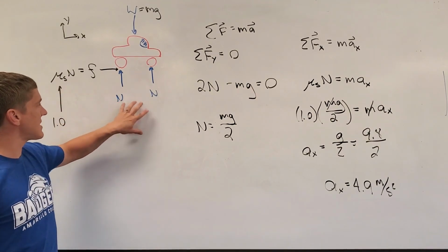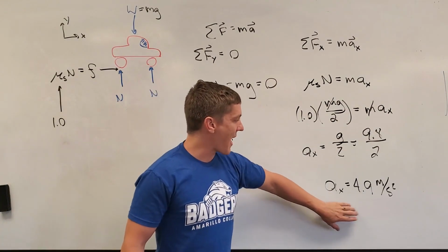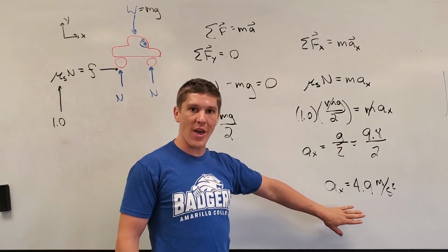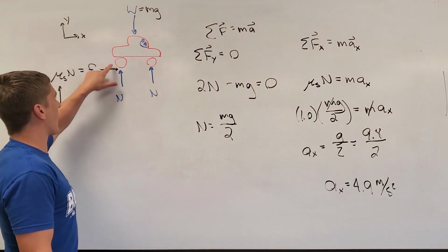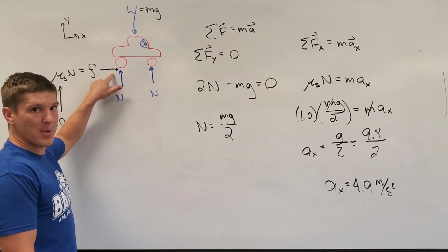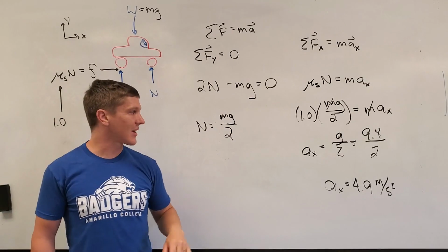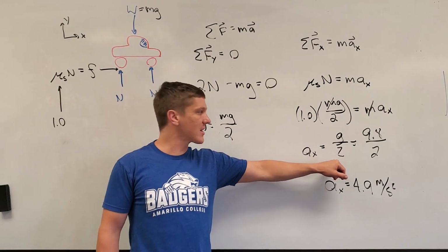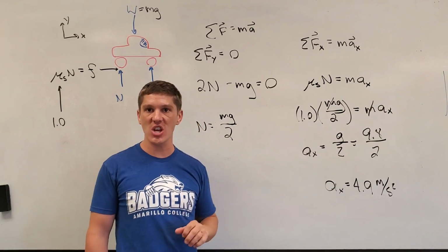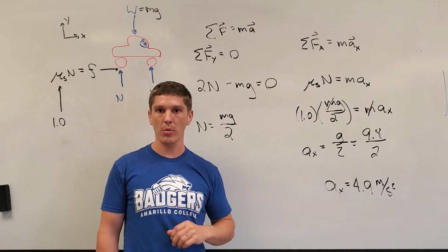With something that seems like minimal information, we are still able to figure out what the maximum acceleration due to the 50-50 weight balance and due to that rubber contacting the concrete would be for this car. In that case, it's going to be 4.9 meters per second squared, or half a g. So a typical car can accelerate at about half a g, which would be the maximum acceleration that you could get from a standard rubber tire.